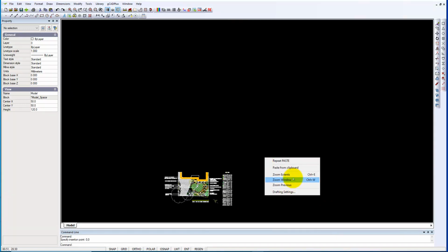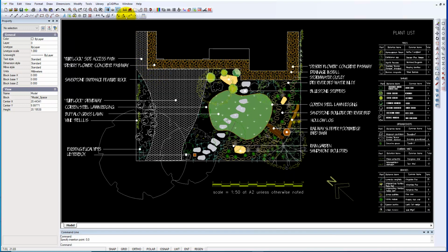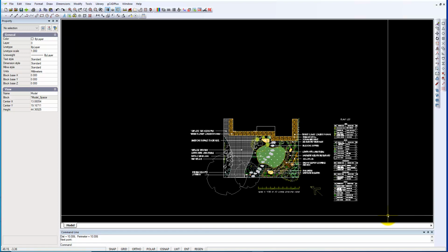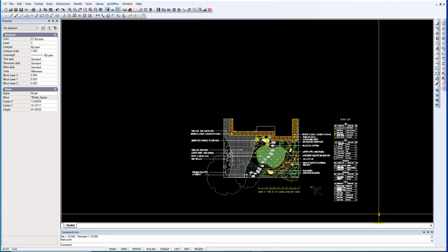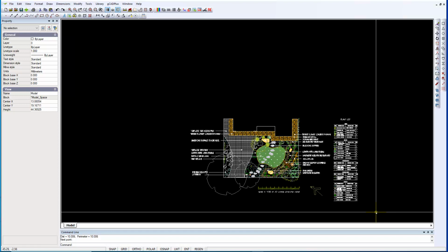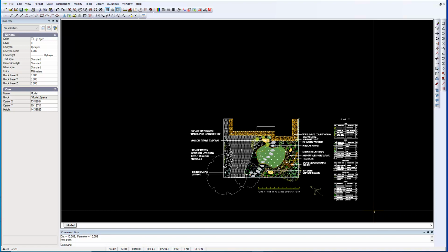and now I can zoom extents. We still have the same problem. Let's go from one side to the other, and we get 10 units. So 10 meters. We need to change everything to millimeters, because in the building trade in Australia and many other metric countries, the only time you would use meters would be in a very large drawing that's been created by